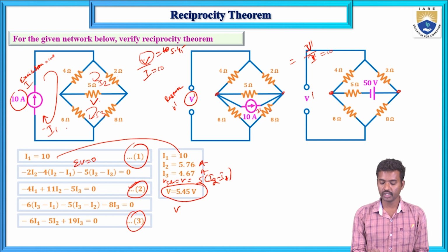Now for this circuit, which is the same circuit, we can calculate the response voltage, but if we use it directly, the circuit complexity increases. First simplify this circuit into a single branch, then we can apply KVL for each mesh. Using the network reduction technique, that is source transformation, we can simplify. A current source in parallel with a resistance is replaced by a voltage source in series with a resistance.